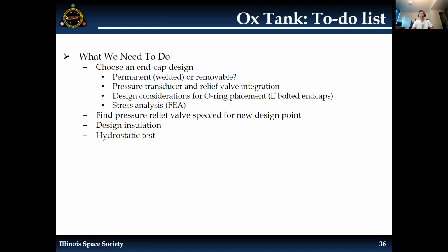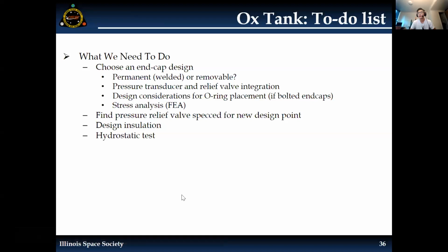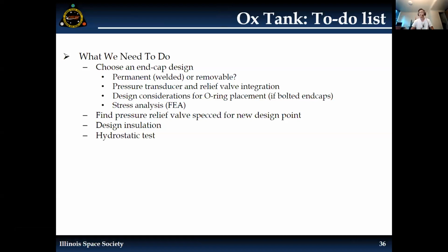Yeah, good questions. So we are designing our tank to withstand 1.5 times the 76 bar pressure. Yes. So 76 times 1.5 will be our maximum allowed operating pressure. But during hydrostatic testing, we're not going to push it to the limit because we don't want our oxidizer tank to fail on us. So 2 times the storage pressure of nitrox is enough for verification purposes.